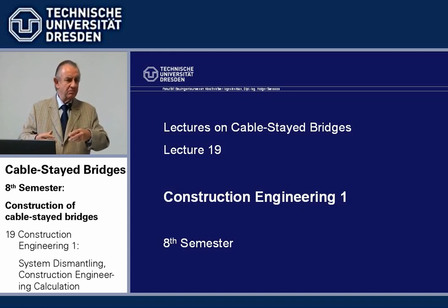I've shown you that for the concrete bridge it is efficient to use the run of moments of a beam which is rigidly supported at the cable anchor points. I've also shown you that for a steel bridge we'd rather choose a different run of moments because that doesn't creep away.